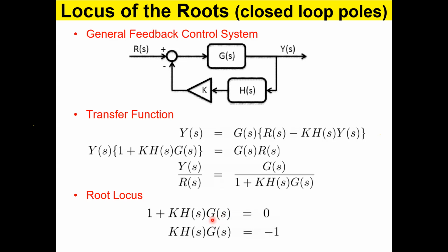Now when you have these roots changing their location as you change k, you can plot them, the position of the roots. Then you get a curve, a line, a path, a locus, basically. Locus, the path. And that is why it is called root locus. So we are going to draw or sketch the root locus of the plant, a feedback control system: as k changes, where the poles are, and as you change the k, the gain here, where are these poles moving?